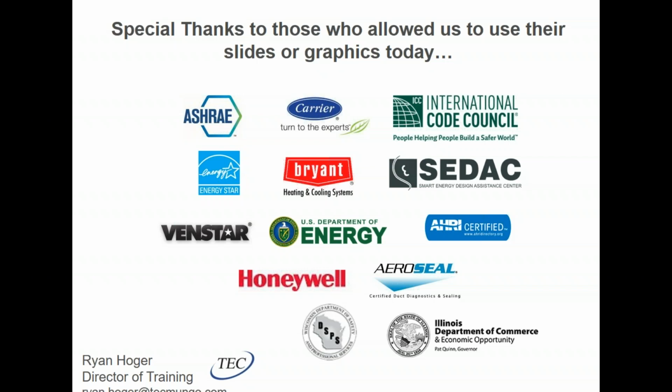There are manufacturers that make kits to do staged air volume. Typically, it's called ARC, Advanced Rooftop Control. It includes a controller, economizer, demand control ventilation sensors, and staged air volume VFD fan. There's three manufacturers that make kits for that.